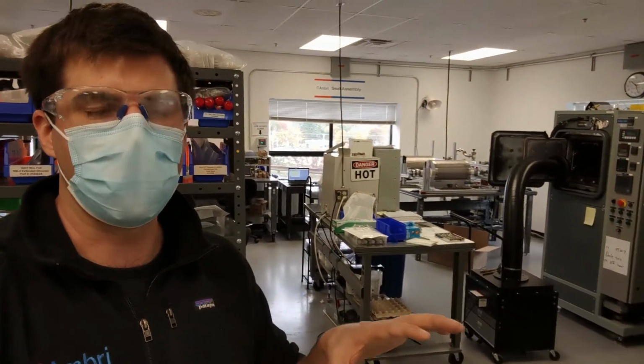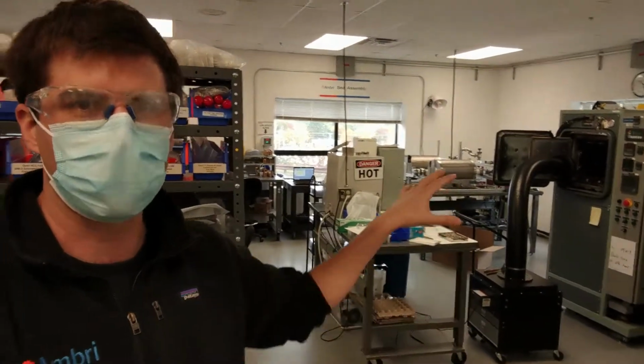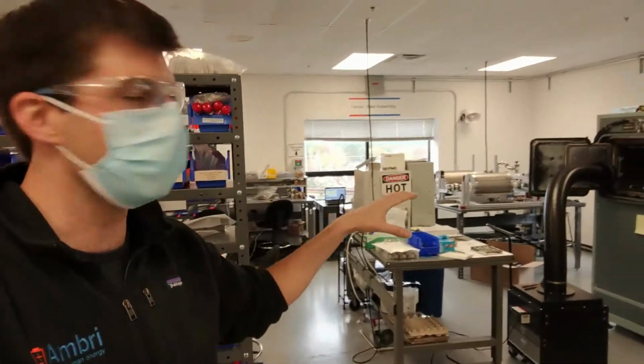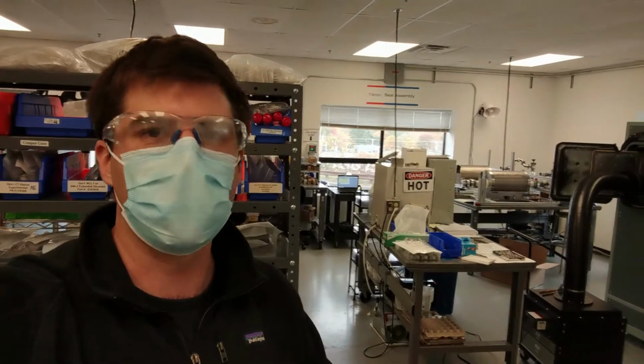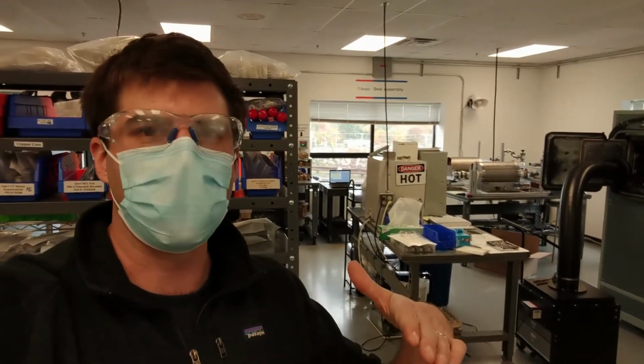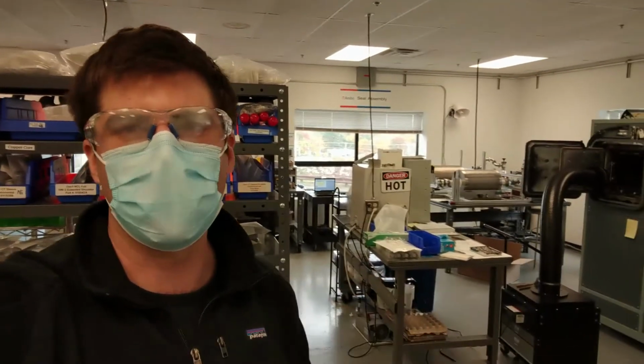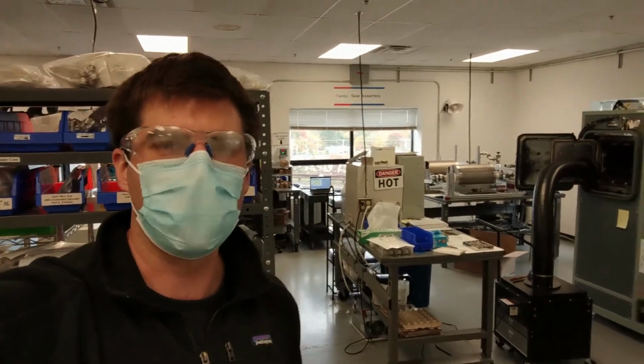Cells are loaded into high temperature vacuum furnaces like the one you see behind me here, as well as the two tube furnaces in the back. And we basically load the components into these furnaces, heat them up under high vacuum, the braze melts, and then forms a bond between the ceramic components and the metal components in our seal.